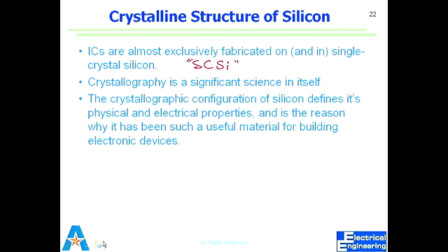Polysilicon can be heavily doped. It acts almost like metals. Okay. Why don't I use metal directly, and why am I going and using polysilicon? Because polysilicon has almost the same thermal behavior as silicon. It's different, but it can withstand high temperature. A metal cannot. So if I need to do some thermal process after I put conductive material, I cannot use metal there. Are you following me?